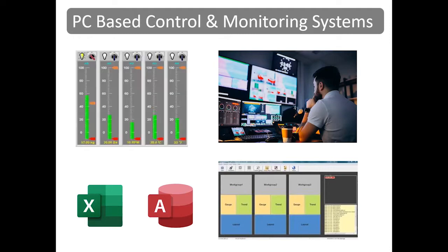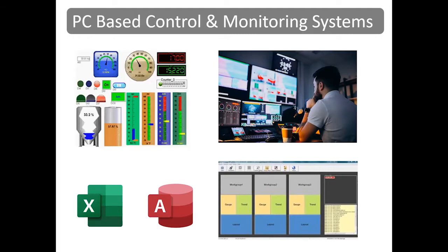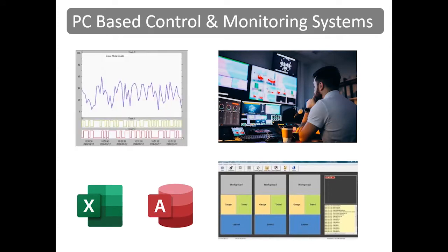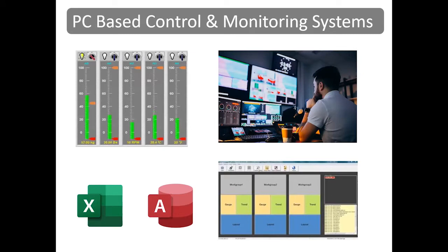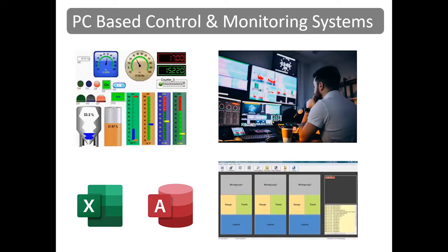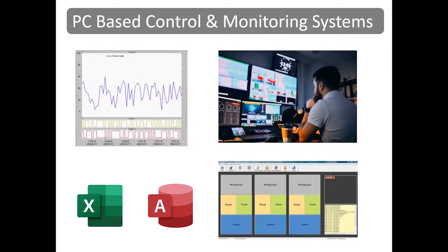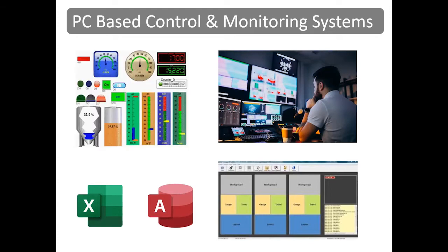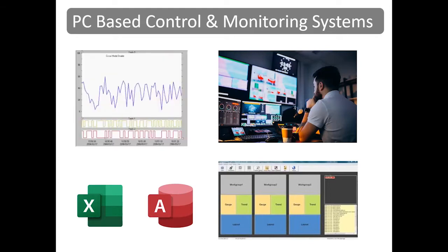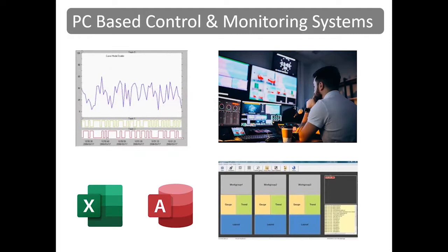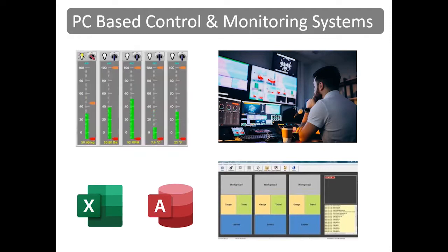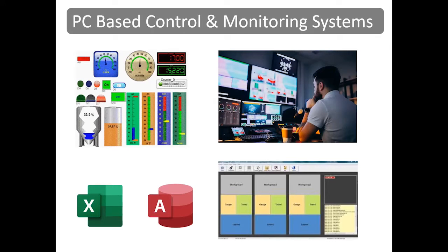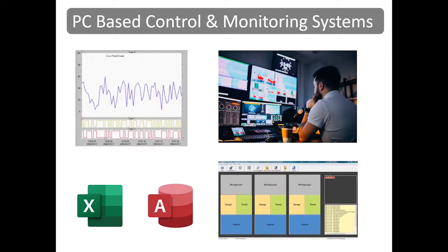Data is collected, stored in a database, and can be exported to Excel spreadsheets. The data can be viewed in trend graphs for analysis and can help show when a door is left open in a cold storage unit, when a tank is leaking, or when data is just out of the expected range. Easy Data Logger is designed for small remote I/O systems with up to 64 I/O tags. More advanced software, Advanced Easy Data Logger, is available for more advanced applications with more tags.